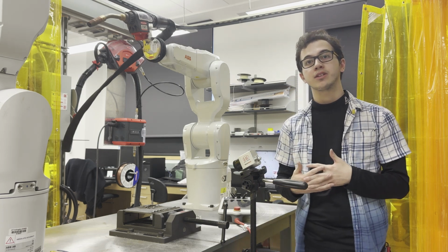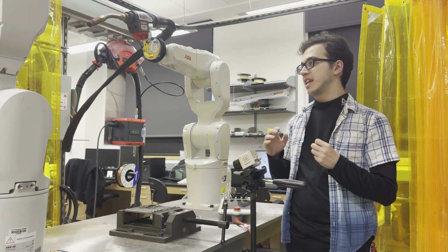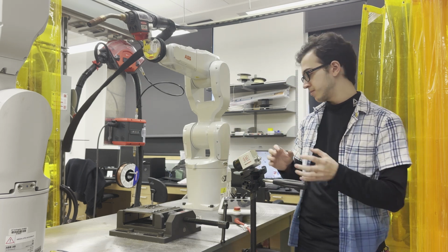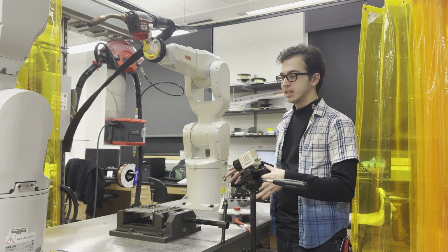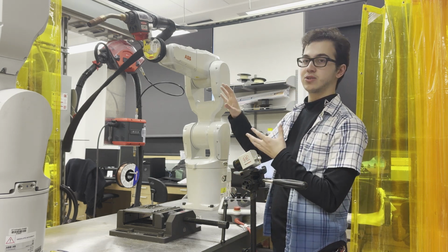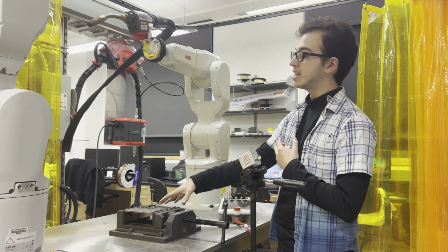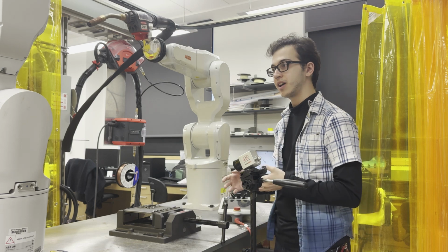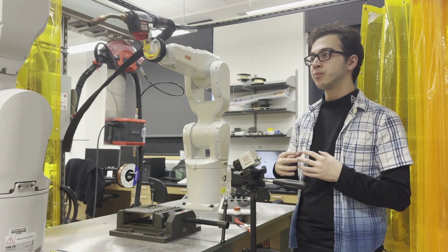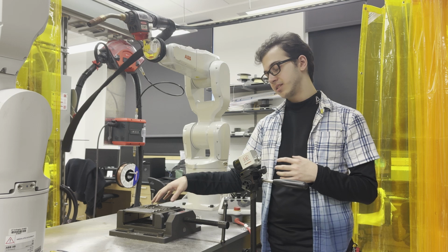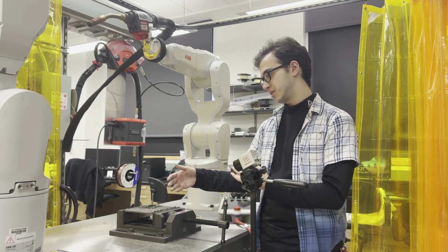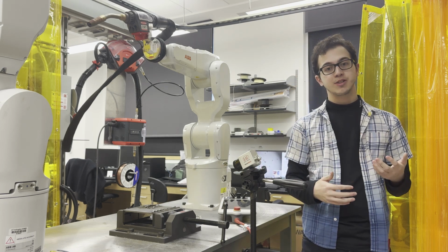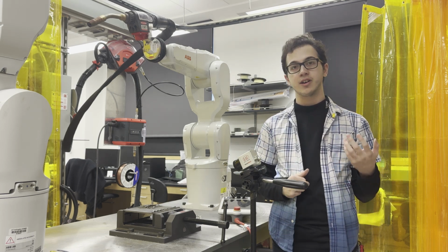Something we'd be looking towards doing in the future is integrating that CNN model, or that defect detection system, into the robot controller directly, allowing the robot to see in real time what is happening on the table and be able to see a defect and detect it. And once it's able to have that smart vision to see what's happening in real time, then we can start exploring concepts of corrective measures.